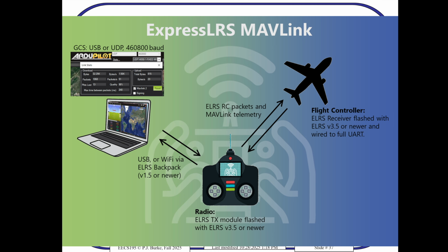Like I said, Mavlink has RC controls as one of its possible messages. But we have 255 possible messages. So now we can get full access to the drone brain. We have Mavlink access to the radio, and the radio is connected to the microcontroller, the flight controller. So now we have full access, and it's two-way. So that's the first step, is to change that protocol and language to Mavlink for the control. And the second step is to forward from the radio to your computer all the other non-radio control packets, and vice versa. So that's what ExpressLRS enables you to do.